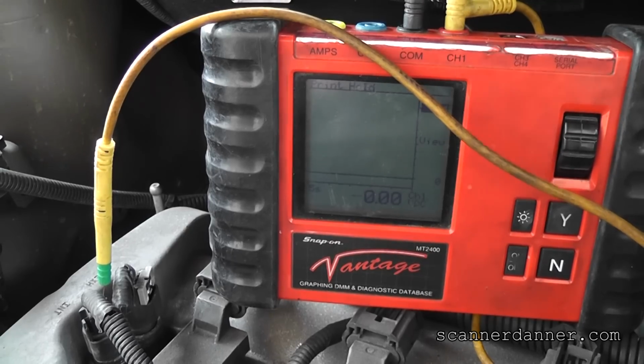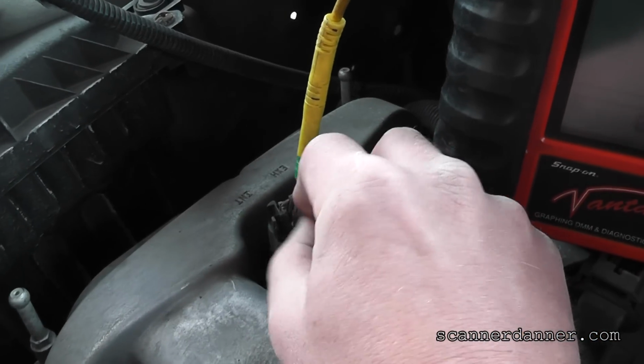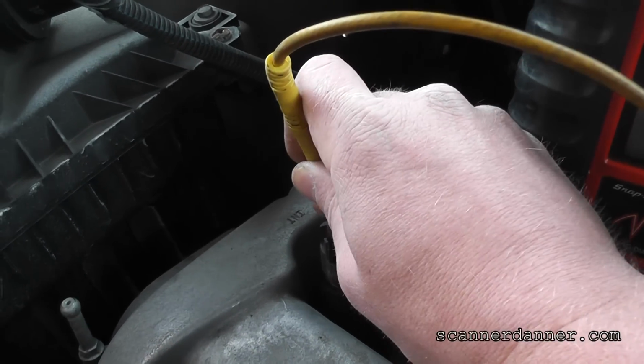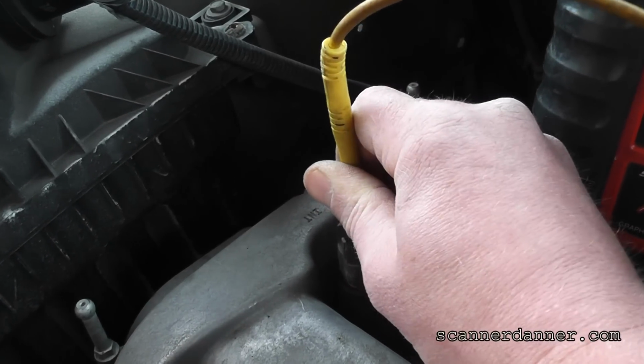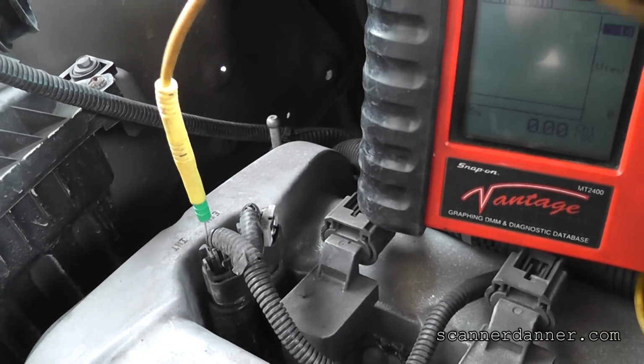So you saw the signal on the feed. The other thing we want to do is check the ground, and the ground would be a loaded circuit test. It's not loaded unless we're commanding the solenoid on. So we get on our ground wire now. That's grounded by the computer.